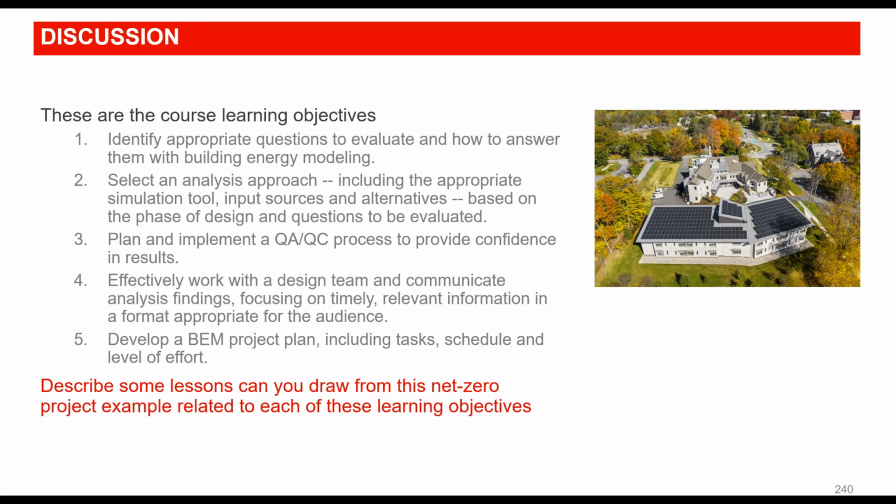Tiana says, considering that occupants may not follow operational practices set, should the building be modeled to take that variability into consideration? I think you can do both and look at the sensitivity of that. If you're expecting that the students may take 50% more showers and use more power, try a model with that and see what the impact is, so that you're not making the assumption to a T, as you say.